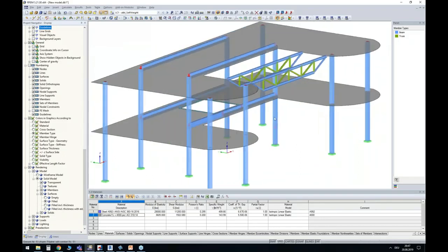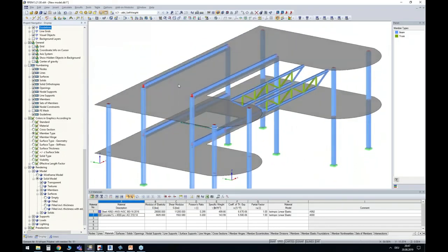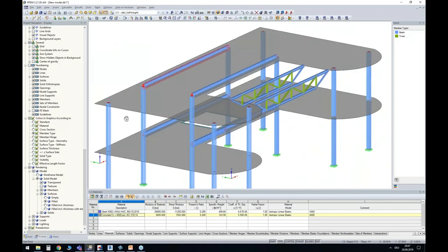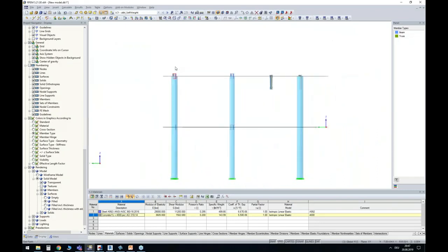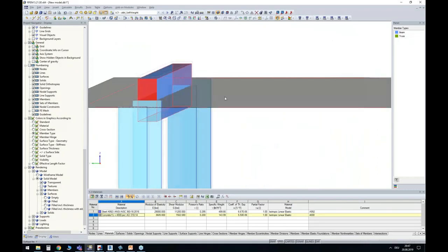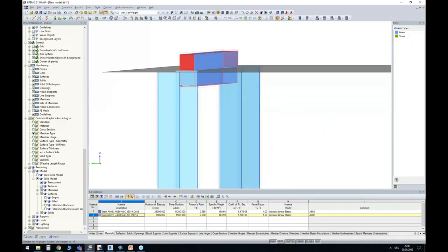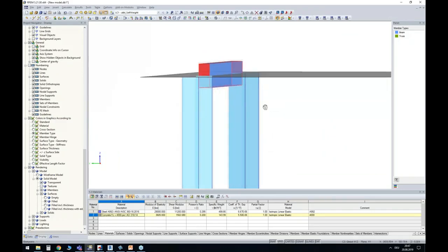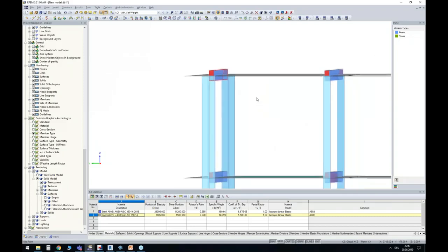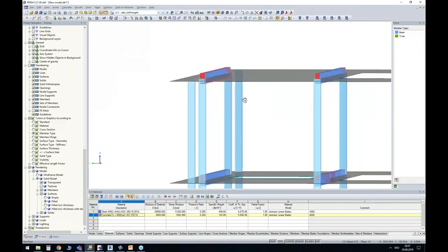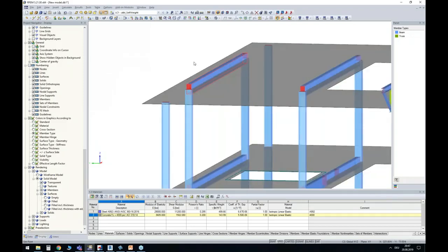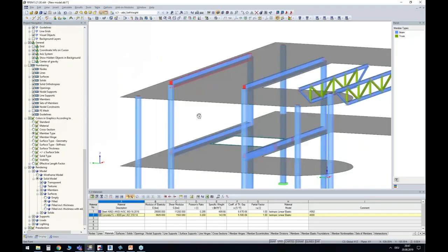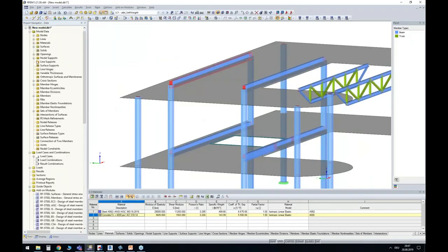And the difference that I see here is following. My beams are placed in the center of the slab, and not eccentric. So the interface doesn't support the export of these eccentricities. It is, however, not a big deal. I can easily change that in RFEM.